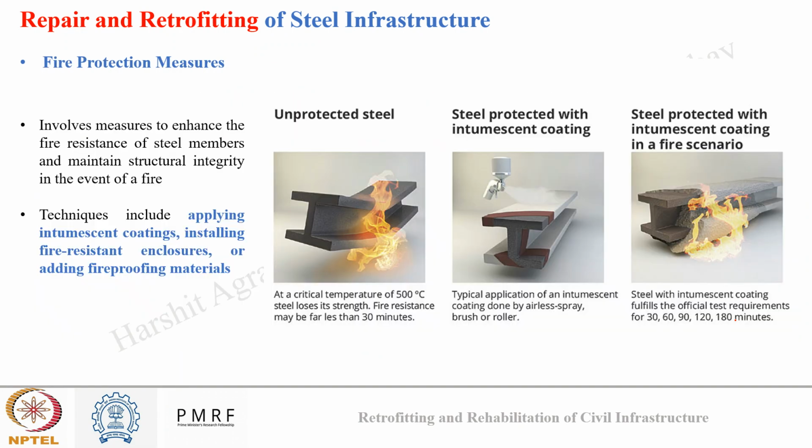And finally, there is fire protection. It involves the use of enhanced fire resistance measures for steel infrastructure to maintain the structural integrity even during fire events. Techniques for fire protection measures include applying intumescent coatings, applying fire resistance enclosures, and adding fireproofing materials.